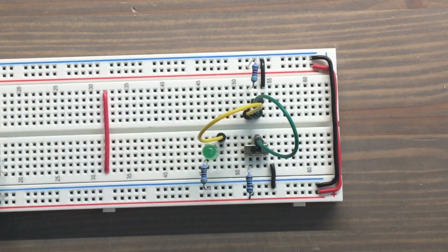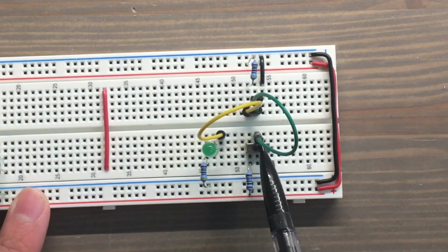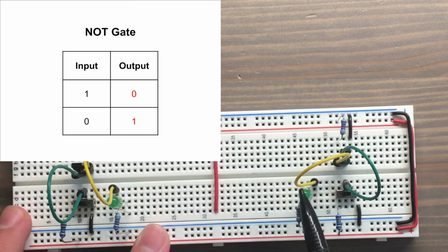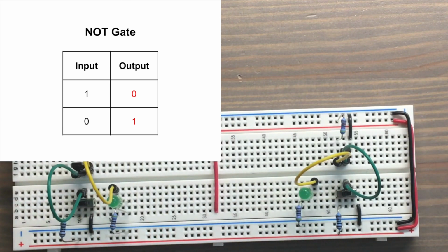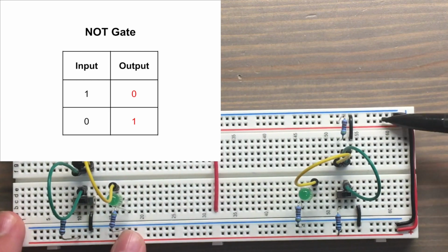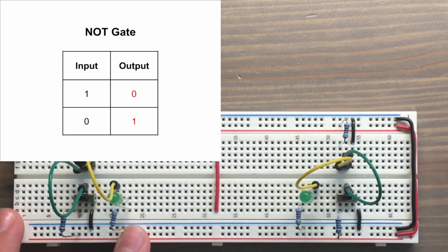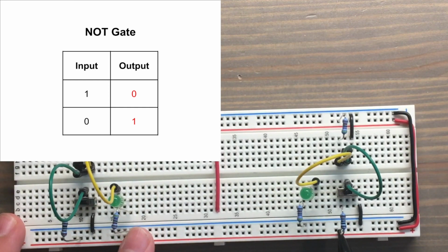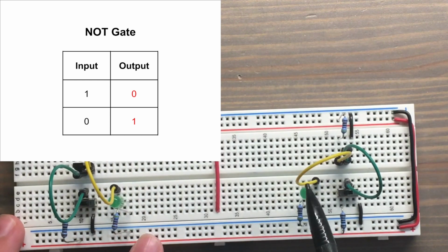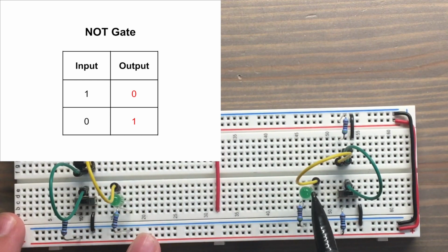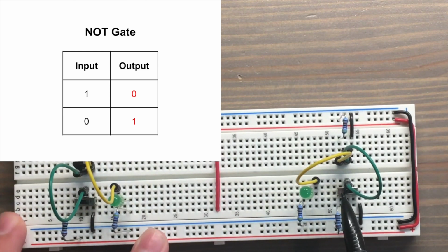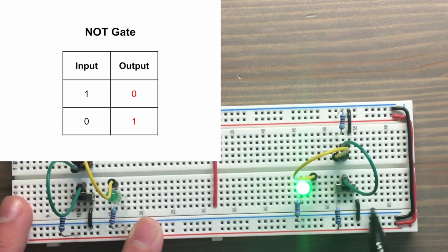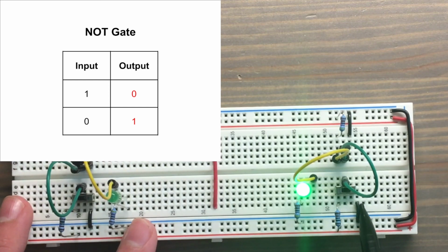Now, the most basic logic gate is the NOT gate here, or an inverter. So basically, whatever input we have on this switch, the opposite will come out on the LED. For this video, we can think of power as a logic 1 and ground as a logic 0. Our switch, since it's connected to power right now, is a logic 1. Because it's inverted, it'll come out as a logic 0 here, which means the LED is off. And if we switch this switch back to ground, the LED turns on since we're giving it a logic 0.